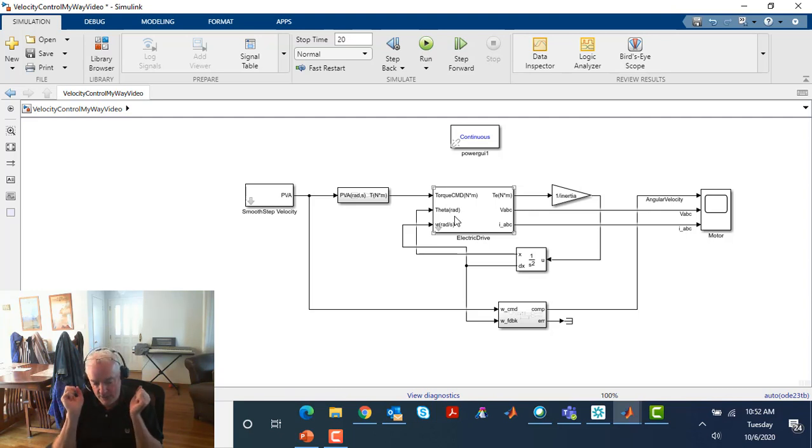Computers are about implementing discrete mathematics, and what that means is that the approximation includes this thing called a delta t. We can definitely get into pretty heavy conversations about accuracy and stability, but let's just say it as easily as we can: things get better the smaller delta t can be. The hardware folks remind you that you have to live in the real world, and delta t really is the passing of time. The real constraint is how fast you can update your mathematics, which is represented by these feedback loops that exist in controls.